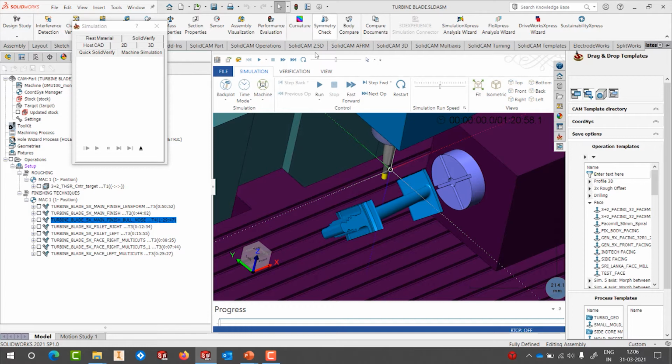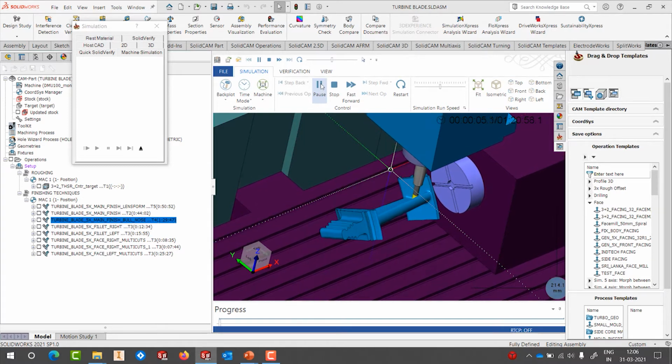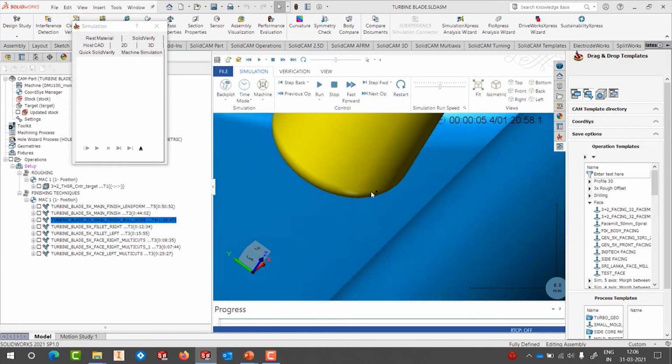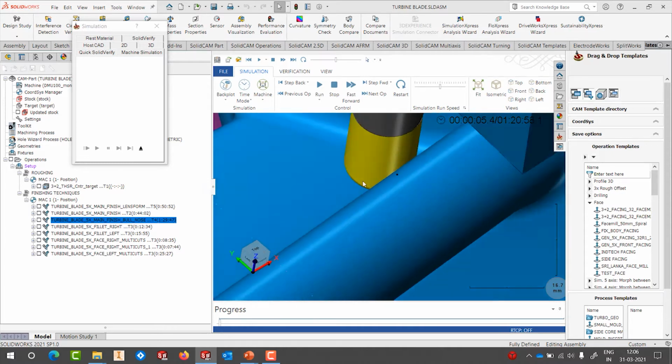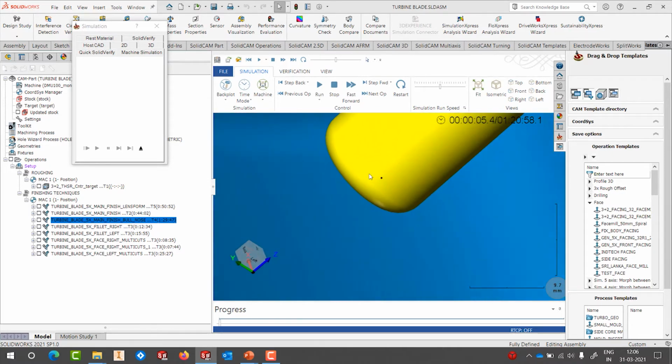And when they are finishing using bullnose tools, they actually use not the bottom of the tool, but they tend to use the side of the tool, because that's where the RPM is and that's where the tool becomes rigid. They can use very high parameters when they're using the side of the tool here.